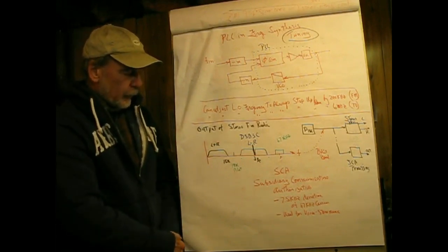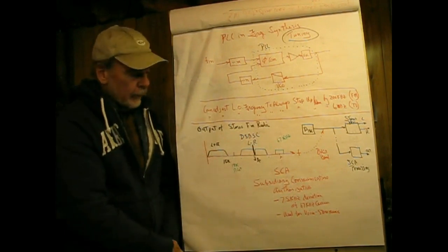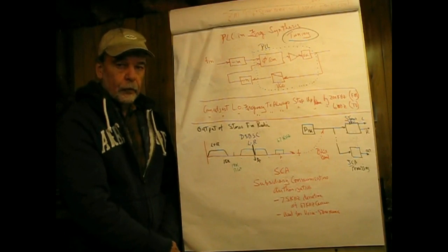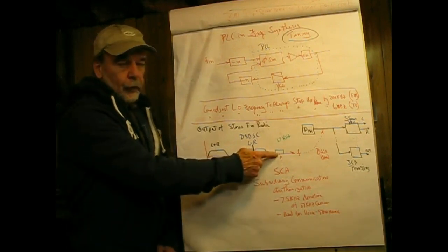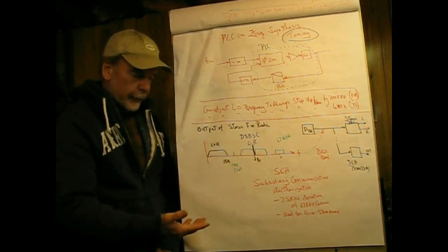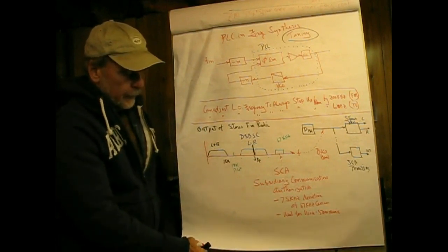The interesting part about this is all of this is frequency modulated, and the baseband contains a type of amplitude modulation, and in addition to that, there's also a frequency modulated carrier which is frequency modulating the main channel. So there's some pretty cool stuff in there.